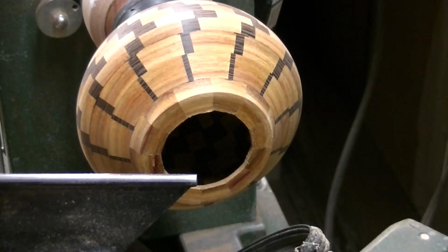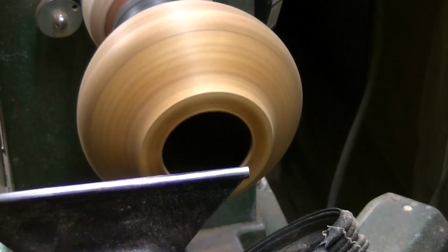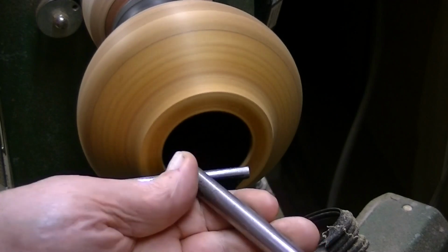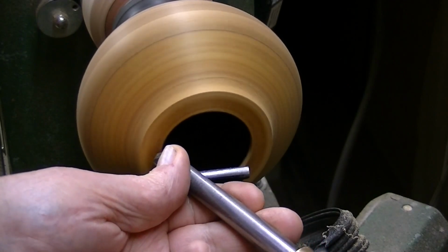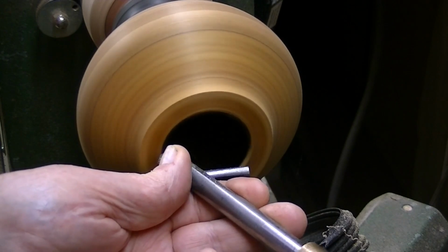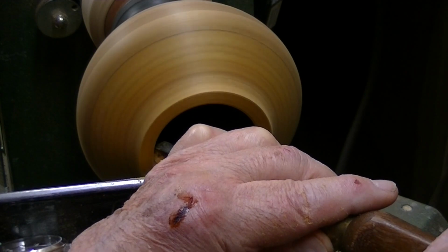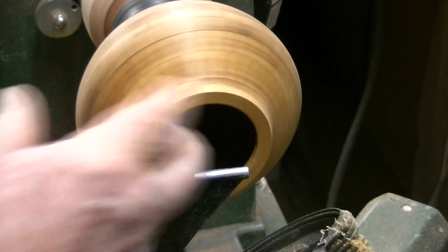So now that that's free, we have to clean up that place where the part was just made. And so a few cuts here with my bowl gouge again, one to flatten it, and then to be sure that the diameter of the opening is what I want. Right now I'm just flattening across that area, slightly incaving it into the inside just a slight bit, cleaning up the edge.